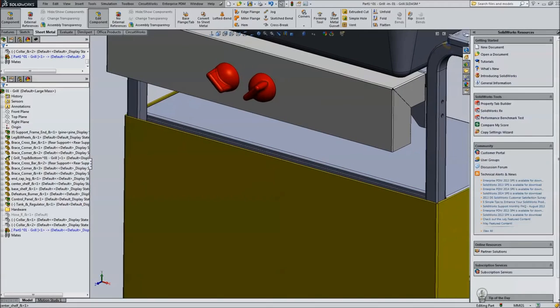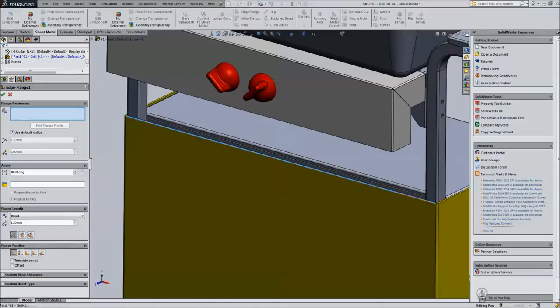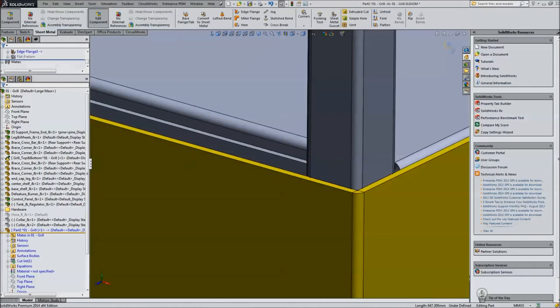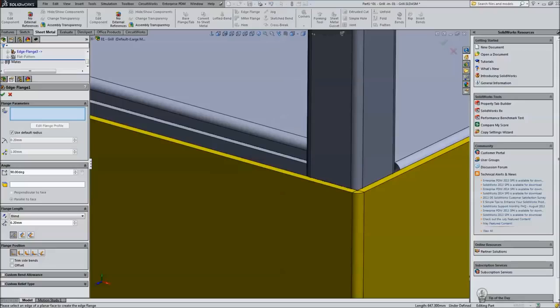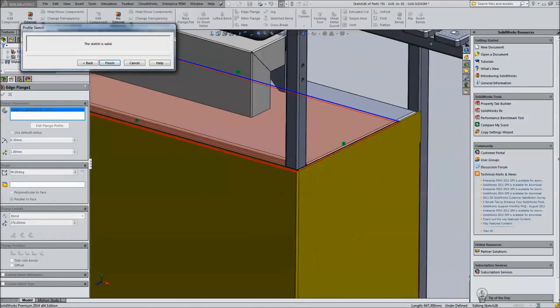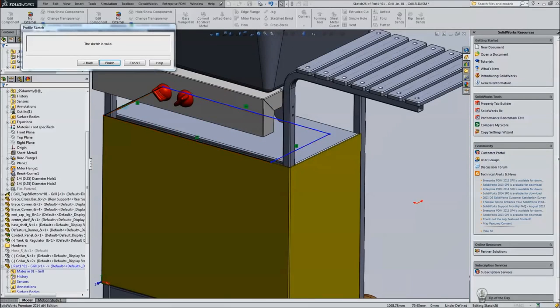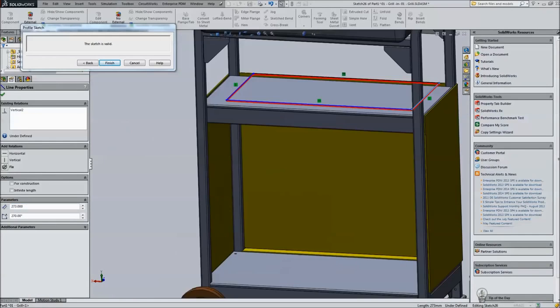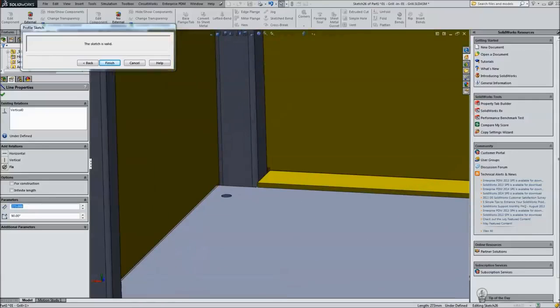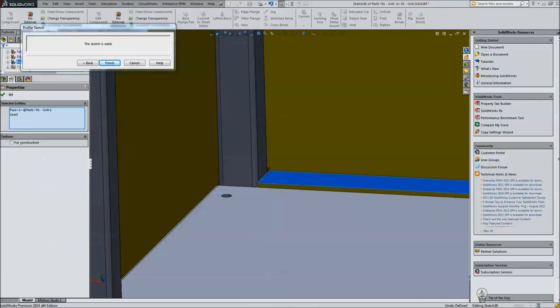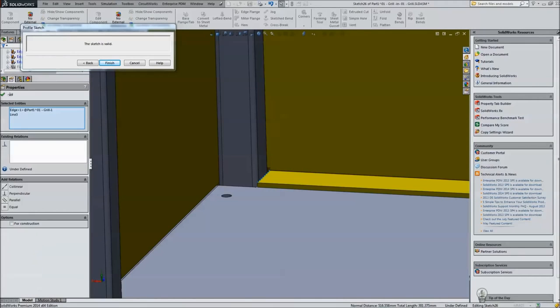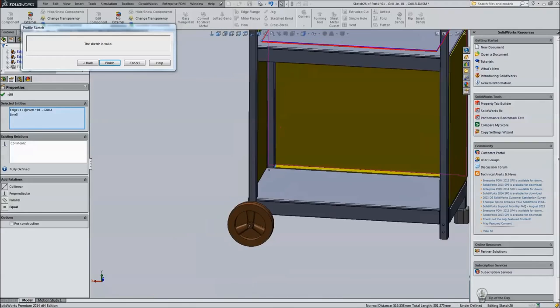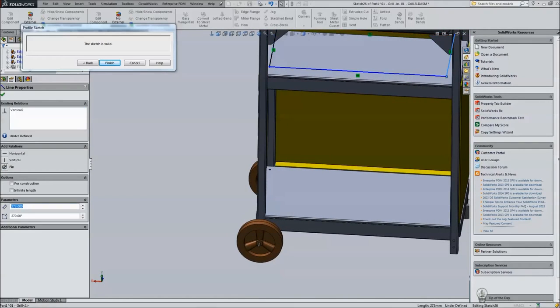And then finally we have the top here. So edge flange. Again, just the same steps we went through already. As long as I add it, let's do that again. Here to here, click on U. Drag U in, drag U in. And this time what I'm going to do, I'm going to pick this flange, pick that edge, make them collinear. I'm going to pick this edge.